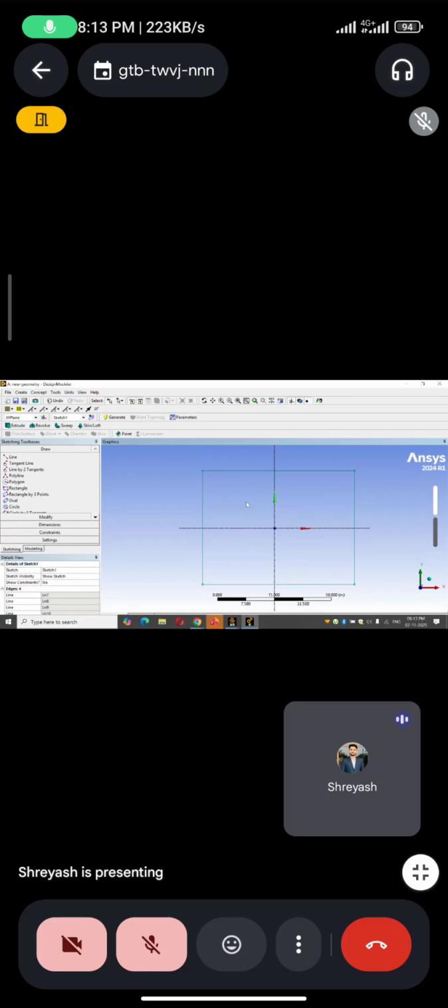Okay. So now I'll give dimensions. Okay. So now what happened? See, there are different options in the dimension. So if I give direct dimensions, it is selected for the whole. Here on the left side you can see it is 30.289 meter. So if I do 20, it will change, but it will not change for the whole.